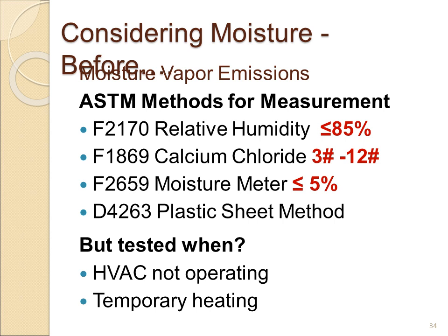When you measure by calcium chloride, 3% is a great number, but typically we're running into concrete slabs that are around 5 pounds as opposed to 3 pounds. 3 pounds you might see in an older installation. And then up to 12 pounds for some membranes that could be applied over the concrete. But all products fall somewhere in between that, and you really need to check with your manufacturer to make sure that their product is recommended for that type of condition.